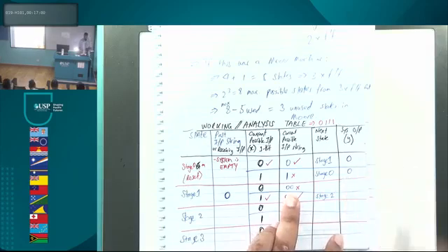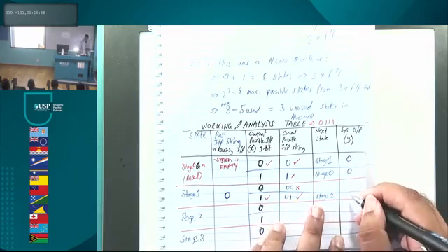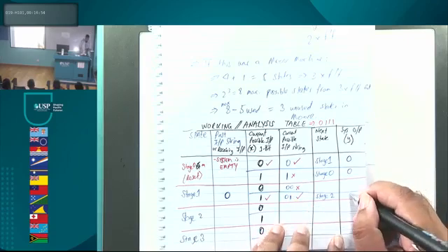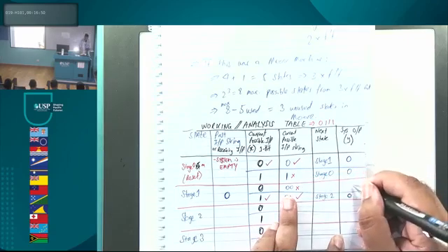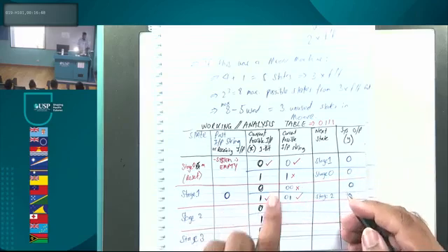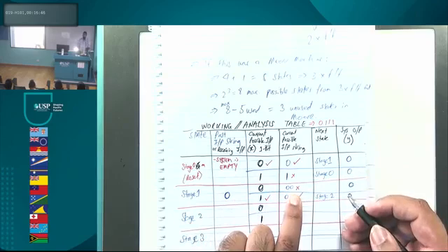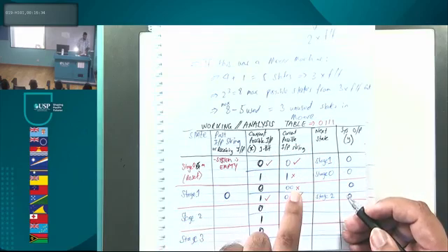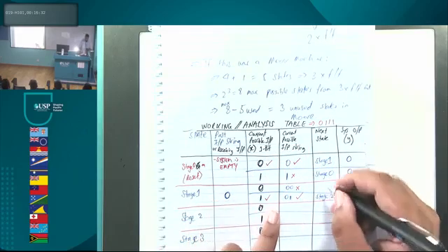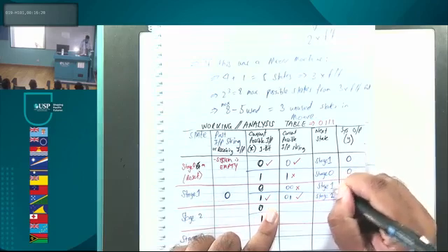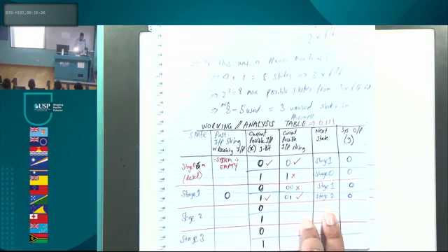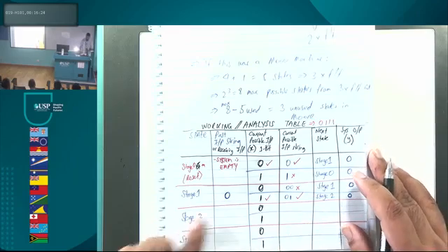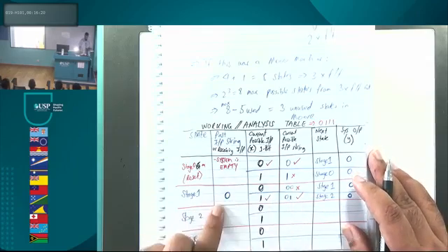0, 0. Can we recycle this? That is the hard part now. Stage 2, but have we got the 4-bit sequence? No, not yet, so that's out. Obviously, this one failed, so he's out. Now, this is the tricky part: what do we do with the failure? We want to recycle it. If we recycle it, this 0, 0, where does it go? Is that 0 useful at any stage? Yes, we used a single 0 over here. So you stay at stage 1. You see this 0? That last 0 can be recycled over here.